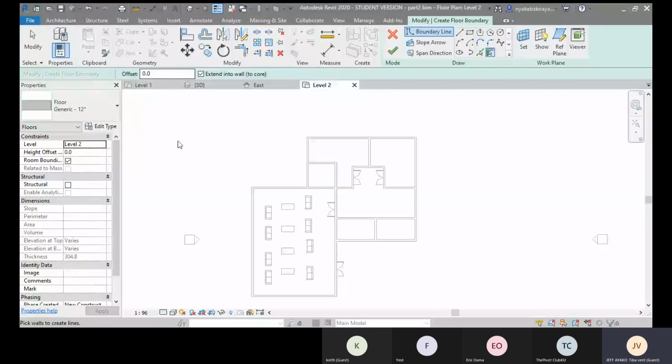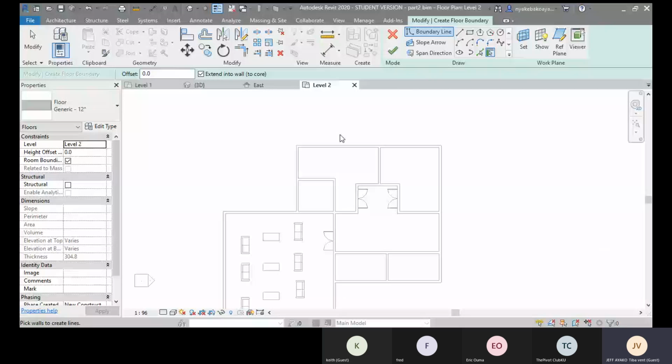let's say you want to offset the extension of your floor outside from your already existing wall. So here there's usually an option to offset. You can enter any dimension there. You can enter, let's say, half a meter, which is 500 millimeters. Click enter. Once you do that, anytime you hover your cursor, it also gives you the preview,